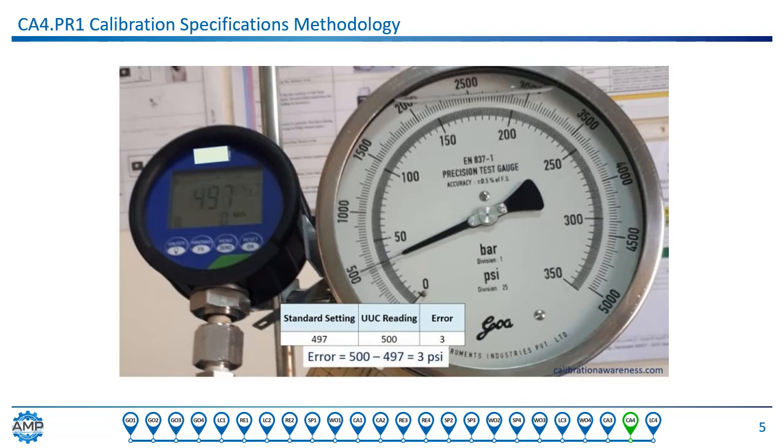All of these things can be included in a calibration specification, both for the benefit of the technician who's performing the calibration as well as the personnel who may eventually audit, investigate, or otherwise need information about an instrument or calibration performance. So basically, when developing calibration specifications, as much information as is necessary to permit a qualified individual to perform or to audit calibration needs to be included.